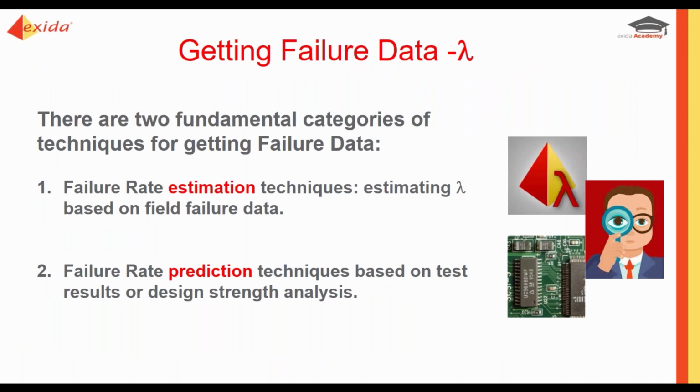So now that we know how important failure rates are, what they are, how important they are, because they protect us, they're our last line of defense of removing that risk before an accident could happen. And we know the standard says they need to be credible, traceable, documented and justified. So now where do you get these failure rates from?